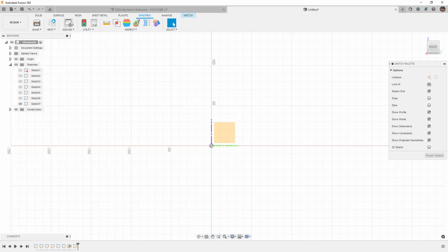So if we run our utility now, you can see that in the XY orientation of the sketch, X being left and right, Y being up and down, we're getting that positive 50 and 50. So we're getting exactly what we expect. However, the trick to this is if we look at the coordinates in the bottom right, X is actually at 120 millimeters because we're in an offset plane. Y is at 50 and Z is at 50.